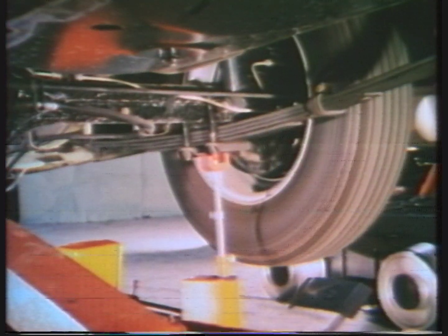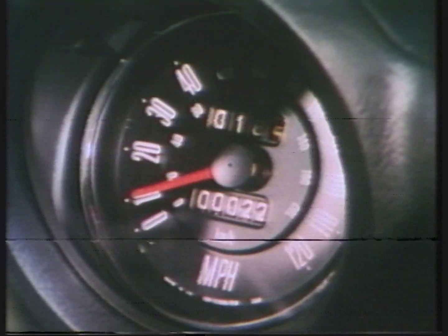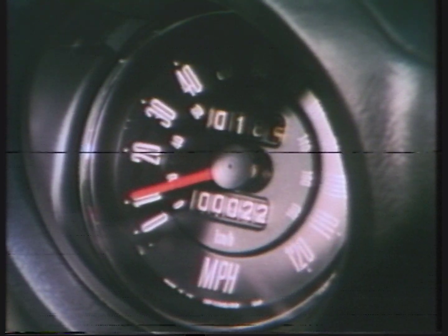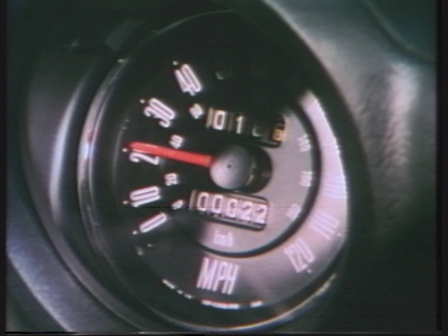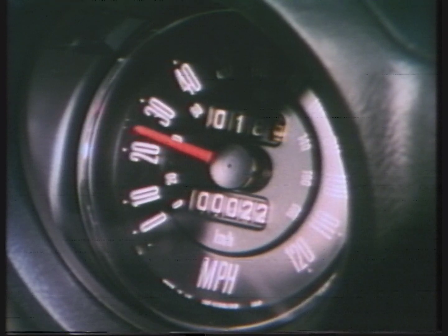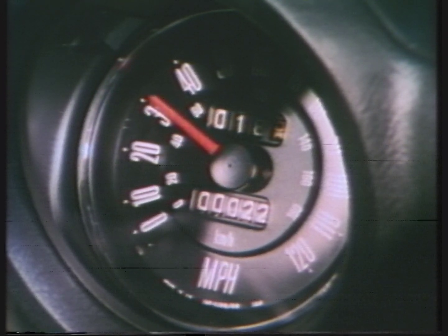The next safety point is that the wheel speed must be monitored on the speedometer the whole time. With top gear selected, the speed is increased slowly until the unbalanced speed is reached, and no more. 35 miles per hour on the speedometer must not be exceeded. This is 70 at the wheel.